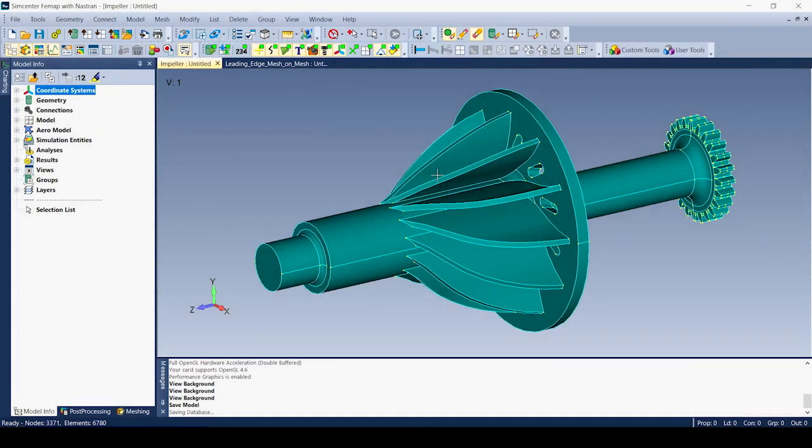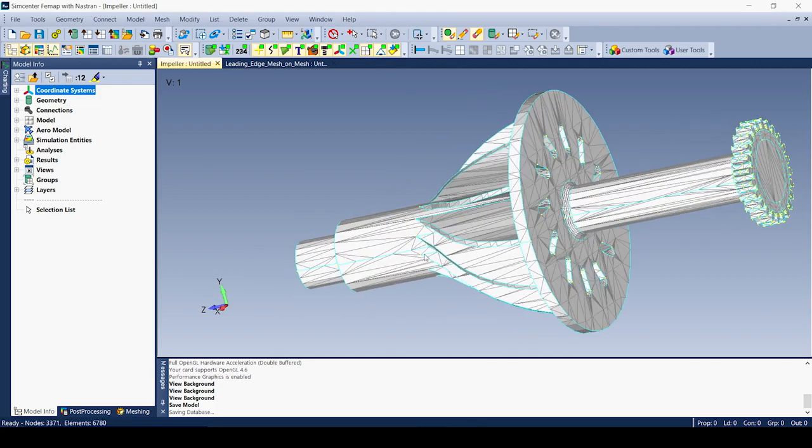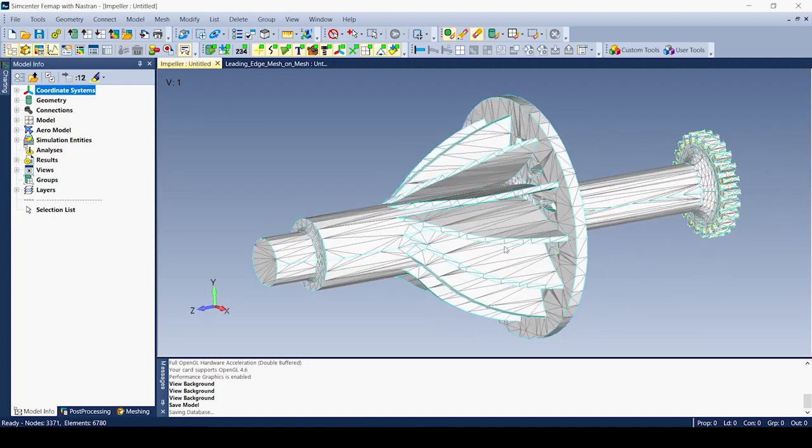Okay, so one of the reasons that we added the mesh bodies command is because more and more we are getting geometry that has facet-based representation for surfaces instead of boundary or B-rep representation for surfaces. This happens to be one of those models. So if I were to take a look at the facets on this piece of geometry, even though it looks like a B-rep, it's actually a piece of faceted geometry that looks like this.